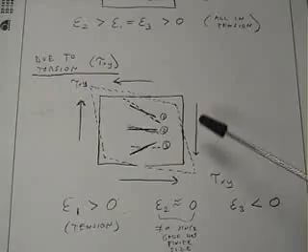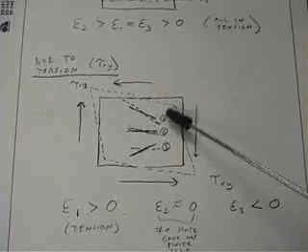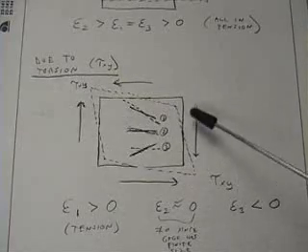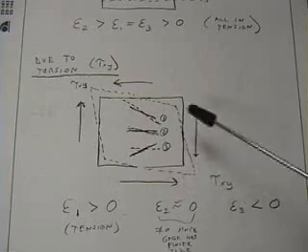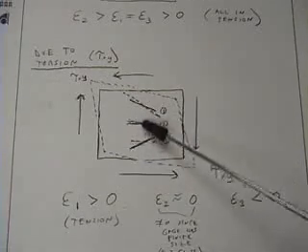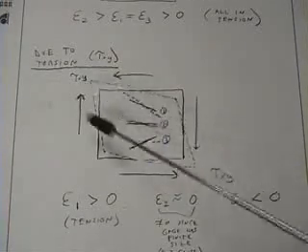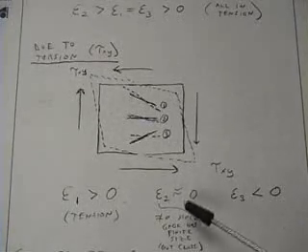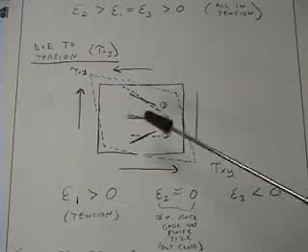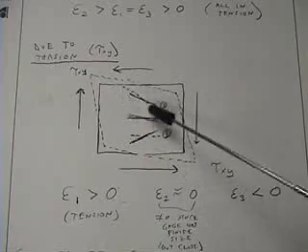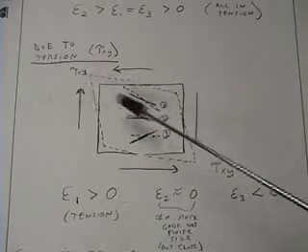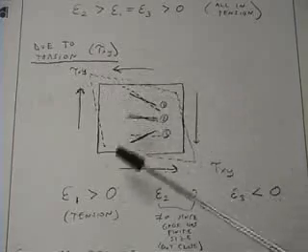Due to torsion, again, we're showing an exaggerated view of how the material will deform as a result of the torsion in this direction. Because gauge 2 is in the center of the rosette and in the center of this deforming element, it experiences almost no strain. Whereas gauge 1 up here is oriented mostly in the shearing or stretching direction, it will experience the most strain.